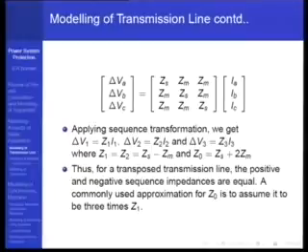And in computing zero sequence, we need to worry about the ground return. Where do the positive sequence and the negative sequence currents go? Does it actually require the ground? It doesn't require the ground, because IA plus IB plus IC is always identically equal to 0. So even if there is a ground, whatever resistance the ground may have, the drop taking place in it is 0. So for positive sequence and negative sequence, we consider the earth potential or the ground potential as 0 throughout, which is a correct representation.